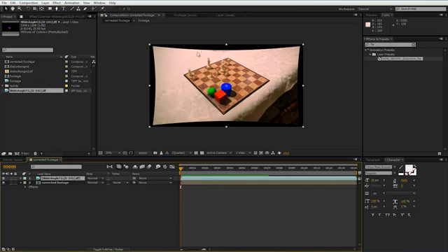Now, ideally, we'd like to reintroduce the lens distortion at 1080, so we could see exactly how much we need to add to get the best possible quality. But unfortunately, because it's using an adjustment layer, because we're using two layers, we don't want to do an individual fix on each. We just want to do the adjustment on one adjustment layer, and everything below is affected by it. And the reason we can't just do it at 1080 is because the adjustment layer works on everything it sees. And if we did it at 1080, the adjustment layer wouldn't be seeing these edges here.